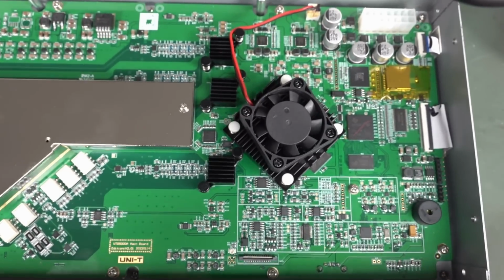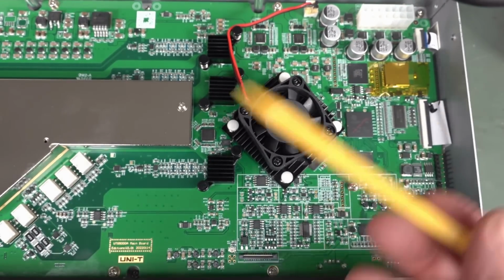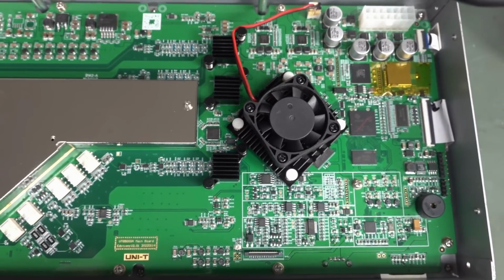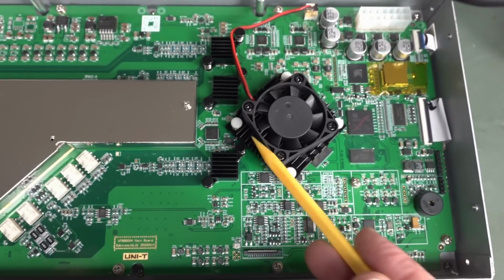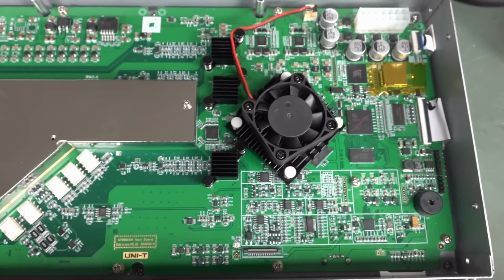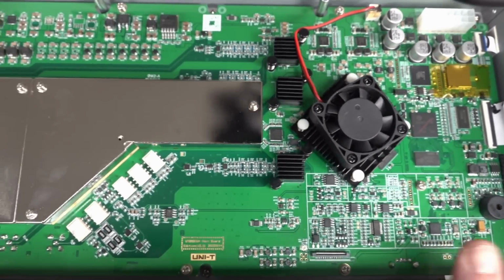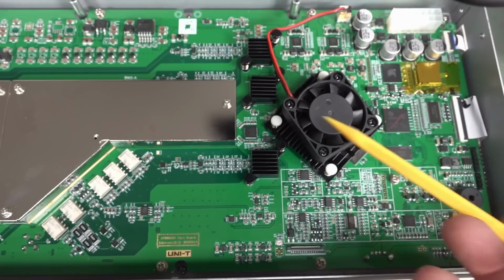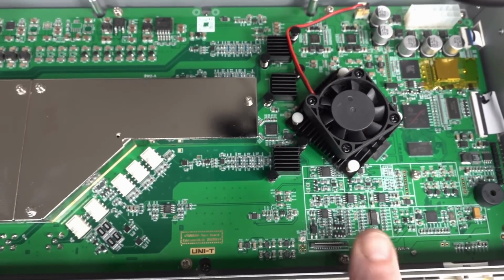I will take high-res photos of this. All my high-res teardown photos are available on the EEVblog Flickr account, which is linked in on EEVblog.com, so check that out. And yeah, we've got one major part here. Is that a big Xilinx Zynq or something like that? I assume it's an ARM processor for doing all the GUI and OS stuff, surrounded maybe by some FPGA fabric.